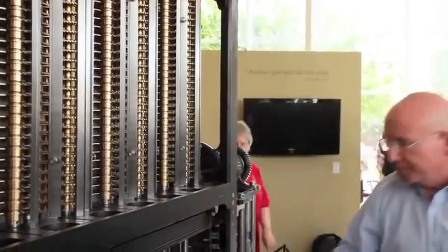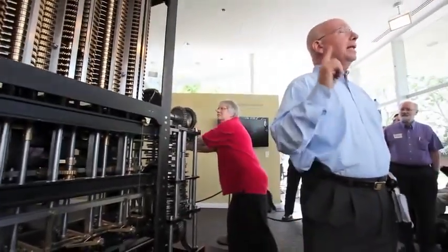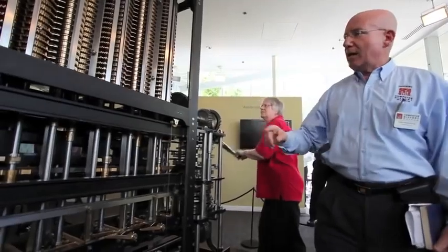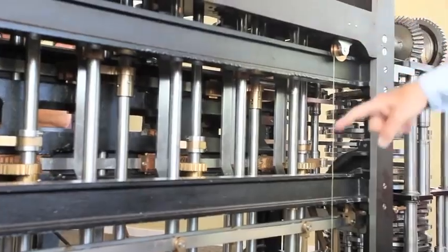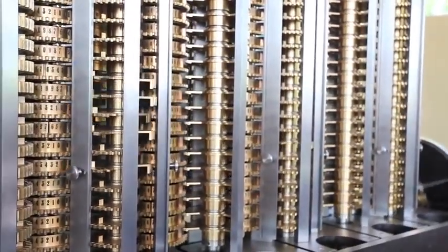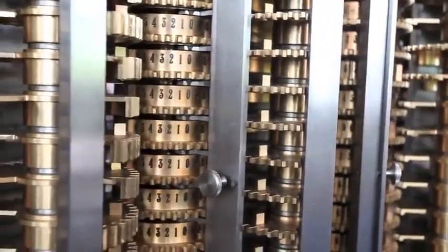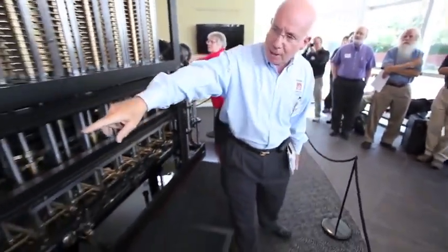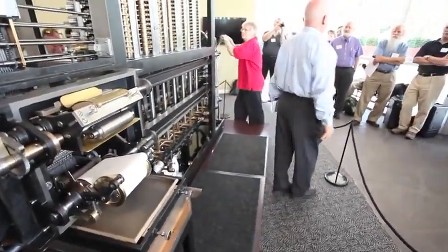Go ahead, Julie. You will also notice this clanking sound. That is the sound of these big interlock blades that run completely up and down the column, snapping in, because when you don't want those columns to rotate, you don't want them to drift in between 2 numbers. So that lock comes in, locks up the column, resets all completely, so you have integer digits on every column. And then you will see the print cycle happen. The type is going to rotate in a second. There's the rotation, print, stereotype, the tray index is in.